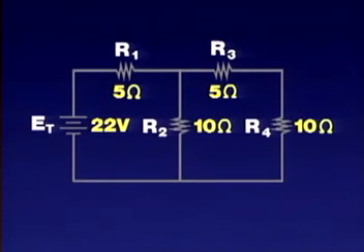Number 1. Many circuits you'll test are a combination of both series and parallel circuits. Recognizing which resistors are connected in series and which are connected in parallel is one of the most important steps in reading schematics. This important step will enable you to simplify a circuit.